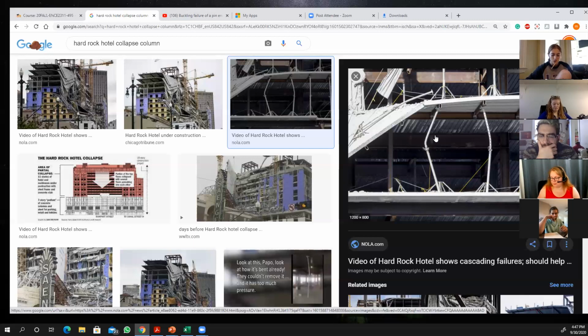If it yielded, for example, if there was not a failure, I can come and replace it and rehab the column. But this is the end of the game. They messed up big time, so there's no fix for this problem. The overall goal that we need to learn from this incident is that you should know how much load you're going to apply to these interior temporary columns, and you need to calculate the applied load on individual columns.